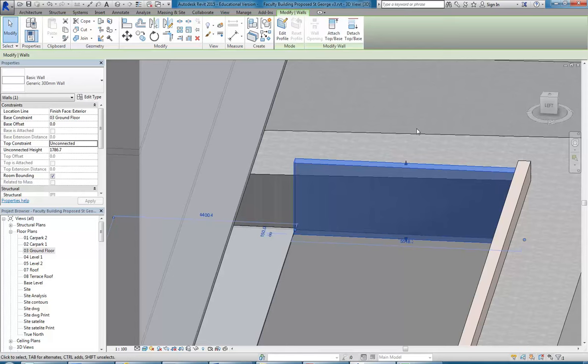And so if it's concrete blocks, they're square, and they're going to step down to follow the slope rather than trying to slope. And even if it's solid, actually, it's quite hard to slope it. If you've got to have a slope done with your formwork, it's fairly difficult. You've got to put a piece on the top that's sloping, and then just think about what happens when you try to pour concrete with the top not being level. It's liquid, and it's quite hard to make that. You can do it, but it's more difficult than if it's level.